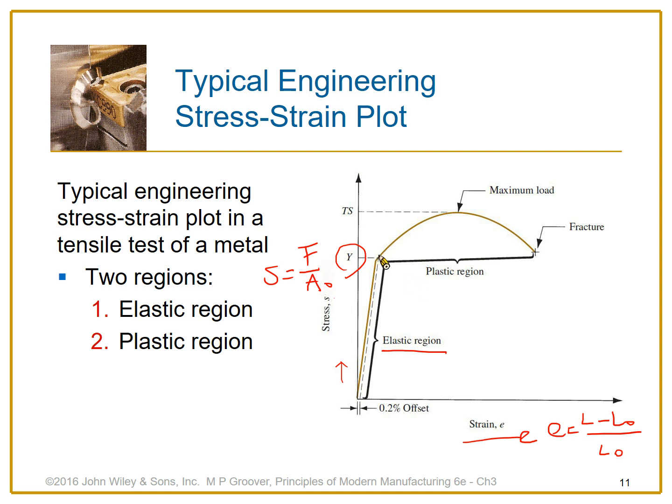That is what we call the plastic region. In this plastic region, as you can see, when we apply stress, the strain quickly increases. That means the change in terms of size is getting larger. Do you see that? Before, it was constant, but after this point, the size change is getting larger. And you keep applying the force until it reaches the tensile strength, which is the maximum loading. Then you see the stress coming down until the fracture. The fracture means that it's broken.